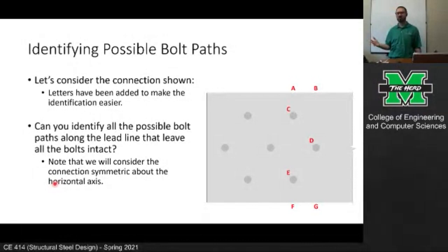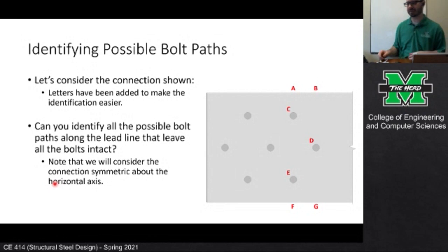The idea is, if you have a truss and a tension member fails, and then the whole truss collapses, that member would be fracture critical. It is a dirty word among bridge engineers because we try to avoid fracture critical systems. If we do include fracture critical systems, they have increased inspection requirements and so on. It's not to say you can't use them, but there had better be a good reason for doing it, like economics. But it's mostly a policy and inspection level issue rather than a net area issue, if you will.